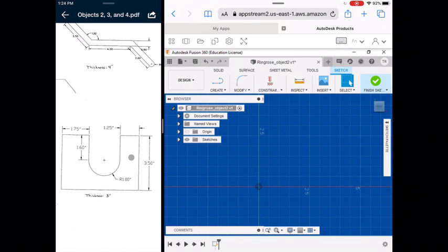So I need to work on breaking this geometric design into the smaller geometric shapes that we can locate inside there. The easiest and most obvious being our circle here, which has a 1-inch radius. This plus sign marks the center of our circle, and R tells us that we're measuring a radius. If we had a full 360 degrees, a full circle, our measurement would be in diameter, but we don't.